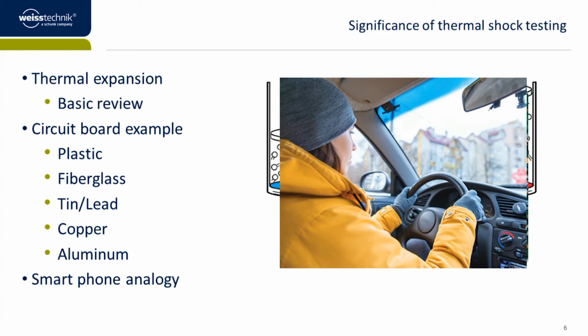And the reason why thermal shock test chambers are used is because we can produce very extreme conditions, very, very hot, very, very cold, temperatures that consumer materials would never see in their normal operating lifetime. So if they can withstand a thermal shock test in one of our chambers, it can be pretty well sure that it's going to withstand the warranty period.